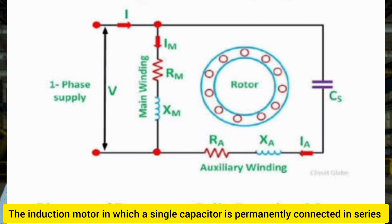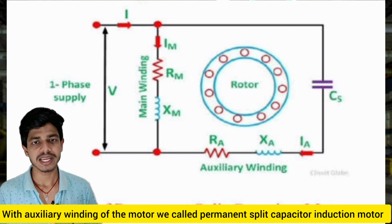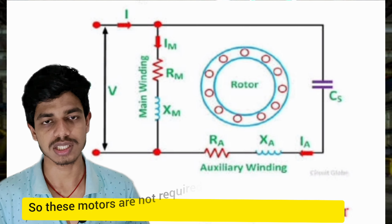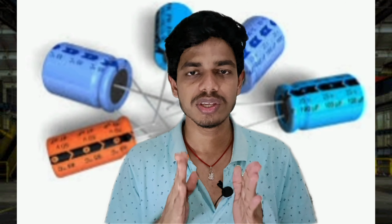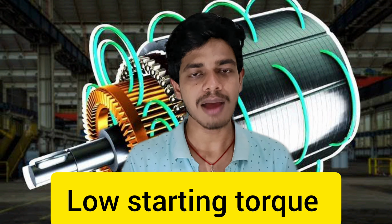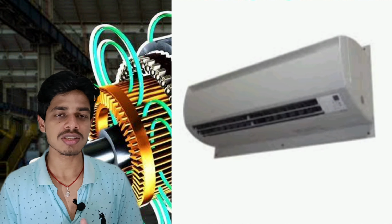Now we discuss the permanent split capacitor induction motor. The induction motor in which a single capacitor is permanently connected in series with the auxiliary winding of the motor is called a permanent split capacitor induction motor. These motors do not require any centrifugal switch. They have some limitations: we can't use electrolytic capacitors, so we use paper spaced oil filled type capacitors, which are more expensive. Another limitation is that they have low starting torque. These motors have various applications like office machinery, water heaters, air conditioners, etc.